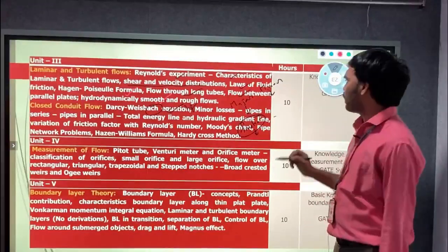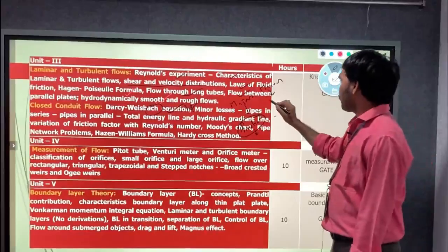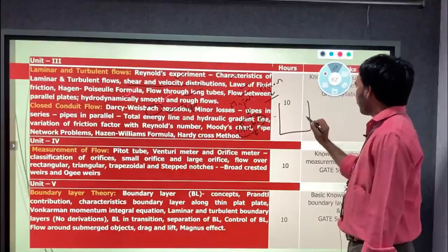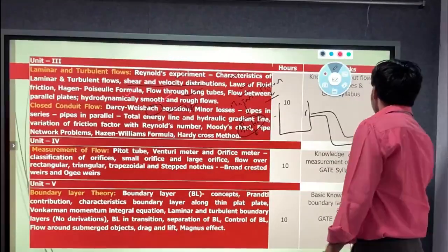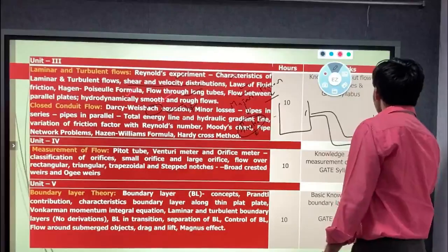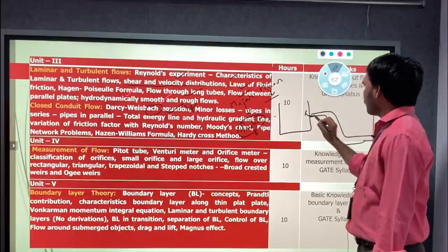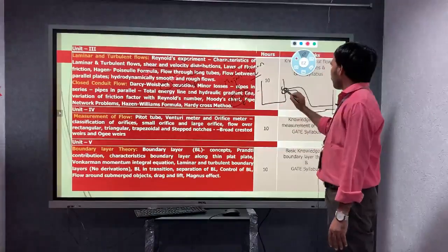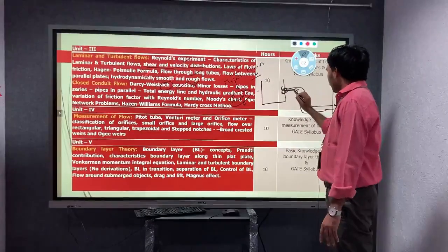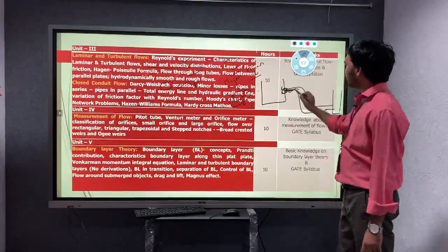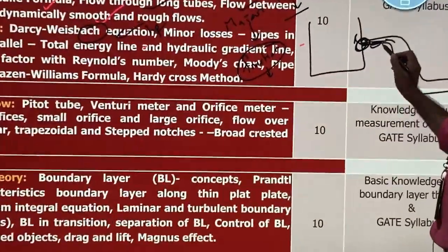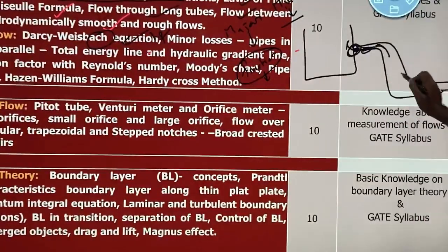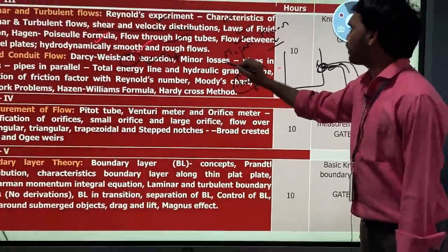And then in the minor losses, we will discuss the various minor losses, like loss of head due to the entrance of the pipe. For example, there is a tank and water is flowing from this tank to another tank. While the water is entering the pipe, because of this entry there is some loss of energy that we will find out. And then once it has entered, there is friction. The friction of the pipe causes resistance to the flow, which will be considered a major loss. At the bend, because of the pipe bend there is some loss of energy, which we will consider a minor loss.